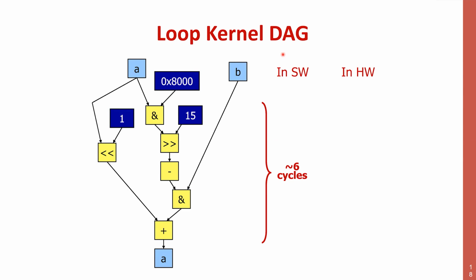How many transistors then for this operator here? Let's think. I have to do A, all the bits of A. So it's a bit-width operator, I hope that is absolutely clear. So in principle, the answer will be, I need to do an AND or NAND, we don't care, per bit. I have 32 bits, I have 4 transistors per bit. So the first not wrong answer will be 32 times 4.